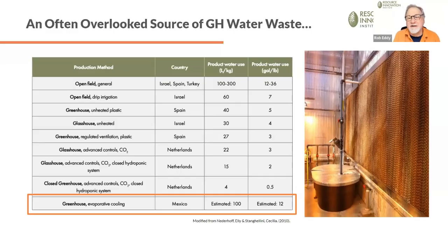And let's talk about that for a minute, because it's something that doesn't get talked about because it's not sexy technology. Here's a beautiful, sexy picture of a brand new evaporative pad cooling system. The water trickles down the pad because there's a reservoir, that black reservoir with a pump, and it trickles water down, and a louver opens behind it, and the fans come on the other side blowing out, so it's sucking in air from behind that pad. As air is drawn across the wet pad, evaporation occurs and cools the room. Oh, it just sounds great and it looks great, but let's look at what it really ends up looking like.